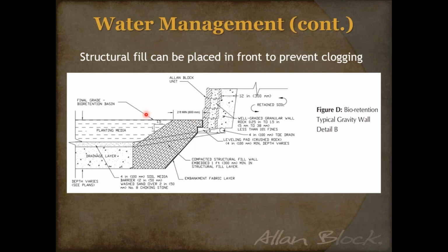But if you do this, now the wall is kind of outside of that soil media and planting media, so you don't have the same concerns. Again, I would still try to vent that wall out because this could be some water table here. We still want to vent that wall out into your drainage area so it's still vented to daylight. So a lot of things to consider.